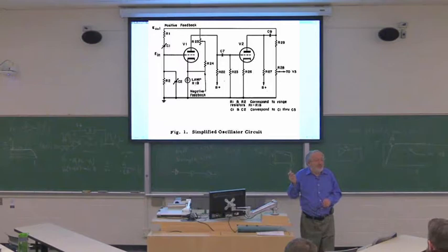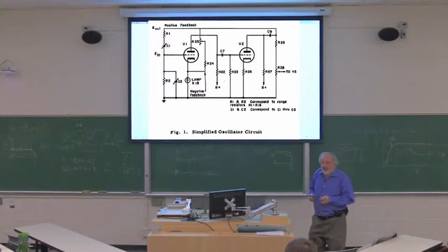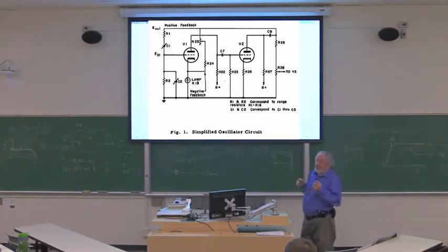It's still one of the best ways to charge rechargeable batteries. You put them in series with a light bulb, so at the beginning the voltage of the battery is low, the current is high, and as the battery gets full, the light bulb gets dimmer and keeps the charging current a bit constant. Anyway, so this student at Stanford put in this light bulb as negative feedback.